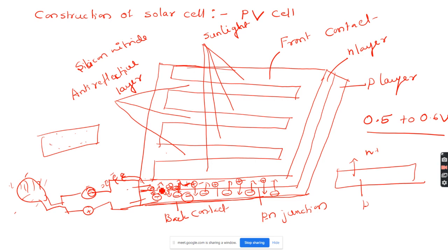First it is doped with P by the surface diffusion process, then over the front side of the wafer, n-type dopant is fixed, so that a PN junction is formed. Over this wafer, anti-reflective coatings are introduced. That anti-reflective coating usually consists of silicon nitride or titanium dioxide.